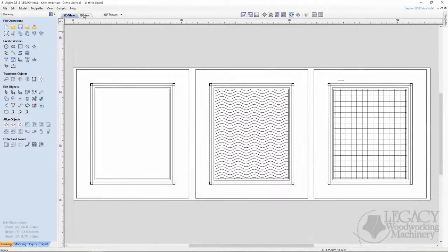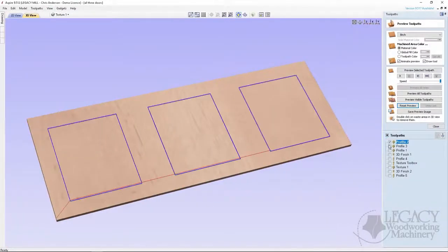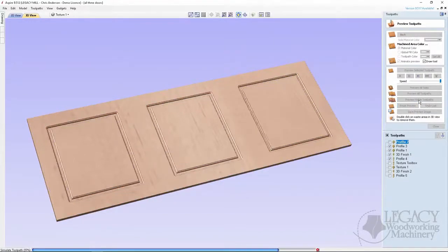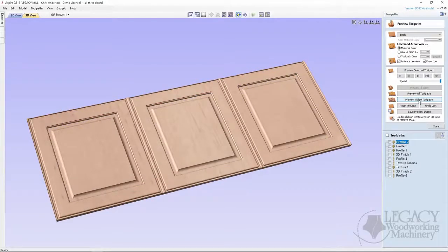Just like in the base cabinet video where we produced the door and drawer front with router bit shape profiles to give us this raised panel look, the same thing is going to be applied to these three doors. The combination of a plunge flat roundover, a large core box cutter, and the tapered ball nose end mill gives us the details necessary to complete that step.